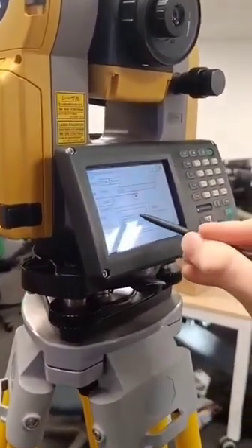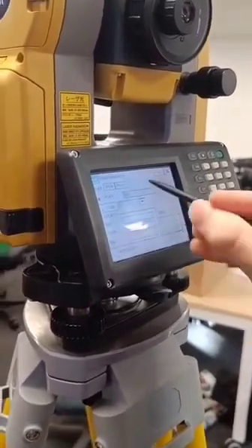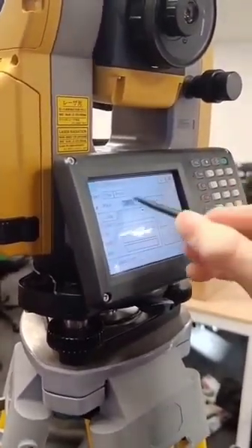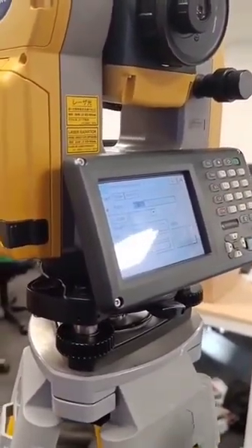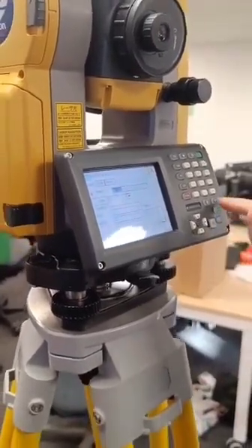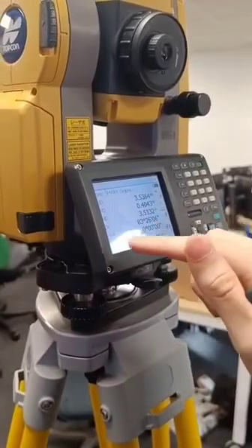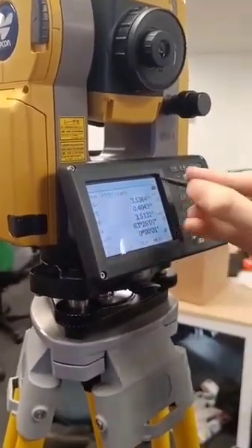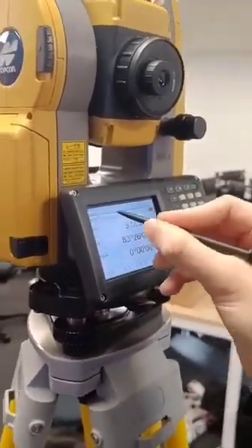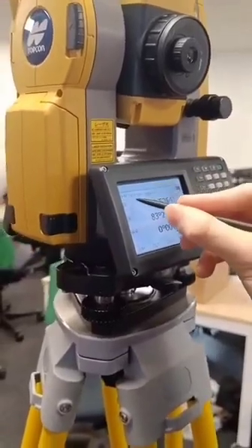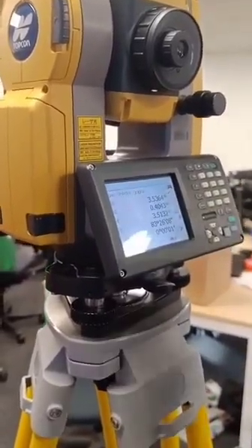And here it tells me all of the information of the backsite, local easting, and I'm just going to change it to BS 100 as the default one, or 01, doesn't matter. And what you can do next, if you hit PRG and you go to, I believe, observe, it comes up with this menu of all your measurements. This could be on default. If you click on SHV dist, that just tells you distances and things.